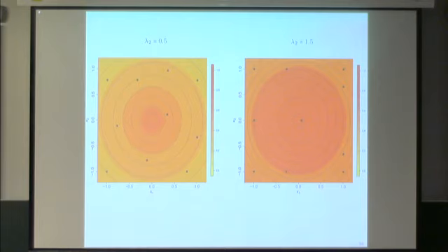Once we have Matern, we can see that the points start moving again to the boundaries, and this is because we have constantly high uniform correlation, and now because we have high correlation in all the design space, the distance between the points doesn't matter, and they move to the boundaries, influenced by the linear trend.